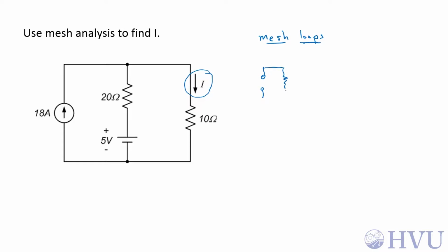Have a resistor there. The voltage source becomes a short circuit. And another resistor here. This is our only enclosed area. This hole in the side makes this not a choice for a mesh loop. So I'm going to define a single mesh loop going around this side. It's going to be I1.